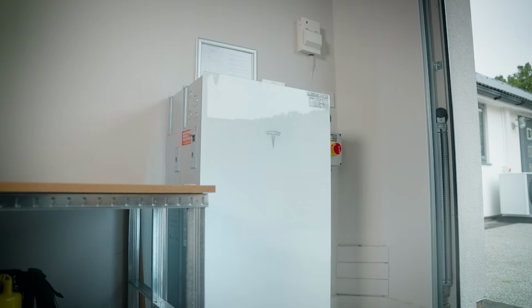We don't want to put it in someone's bedroom next to where they're sleeping. I don't think that would be a wise idea. We don't want to be putting hybrid inverters and battery storage underneath stairs, unless it's got fire compartmentation, for example. And we also normally won't put them within a metre of an entrance or exit inside of a building. Now, you might be going, well, where can I put it? Garages, outdoor places.